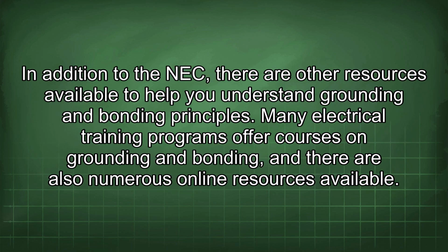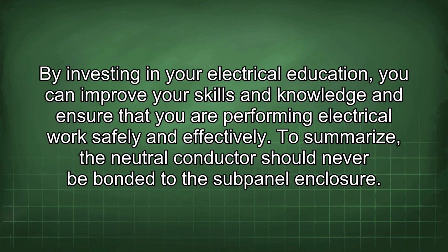In addition to the NEC, there are other resources available to help you understand grounding and bonding principles. Many electrical training programs offer courses on grounding and bonding, and there are also numerous online resources available. By investing in your electrical education, you can improve your skills and knowledge and ensure that you are performing electrical work safely and effectively. To summarize, the neutral conductor should never be bonded to the subpanel enclosure.